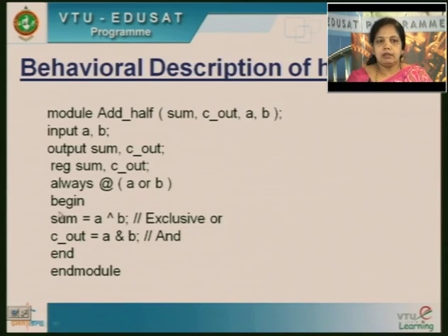Now the begin starts with the set of statements declared here. Before I declare the set of statements over here, I should start with begin. So begin, I will give a statement over here, sum. What is sum here? It's A XOR B. I have used an operator here, the XOR operator. What is carry? It is A and B. So I am using operators here.